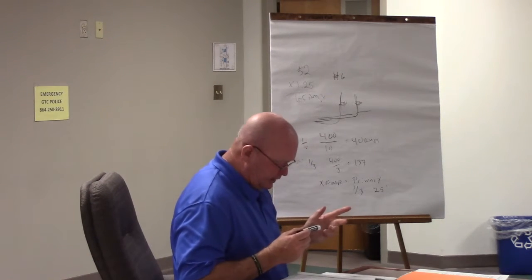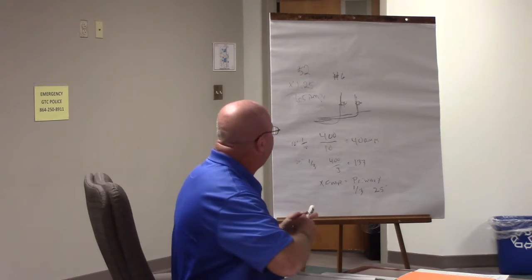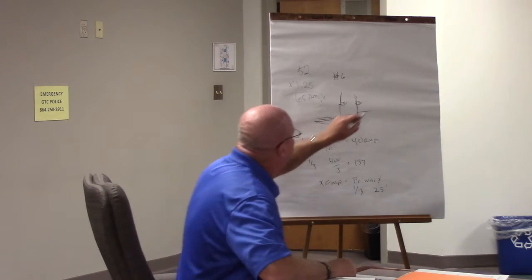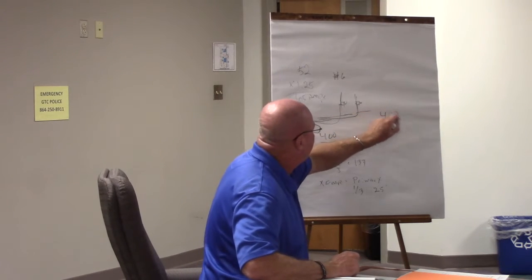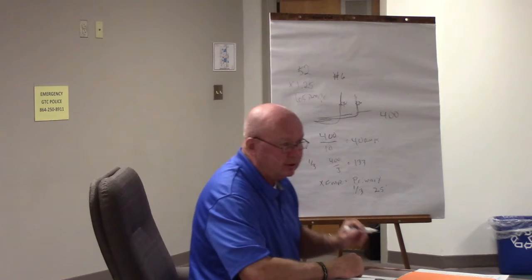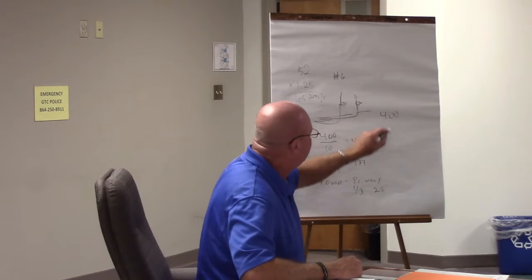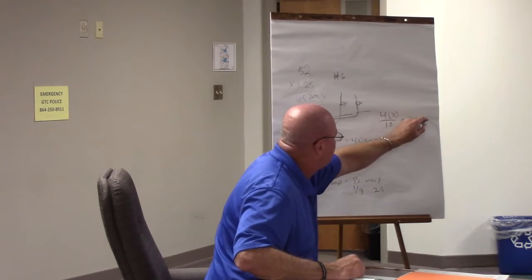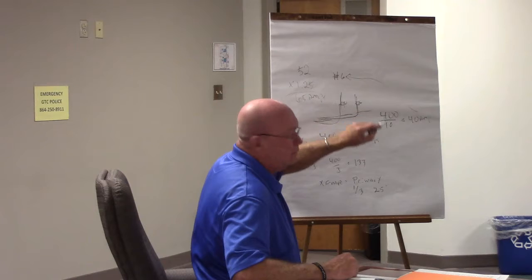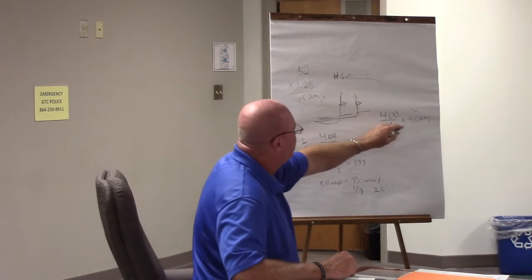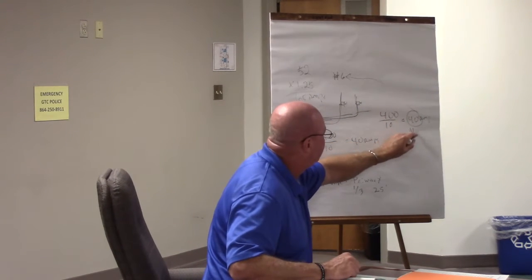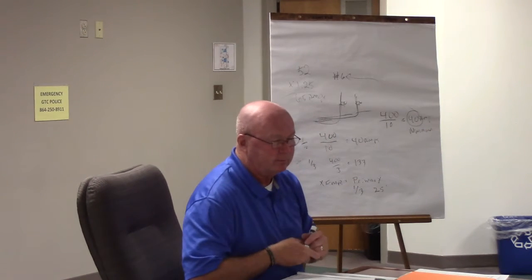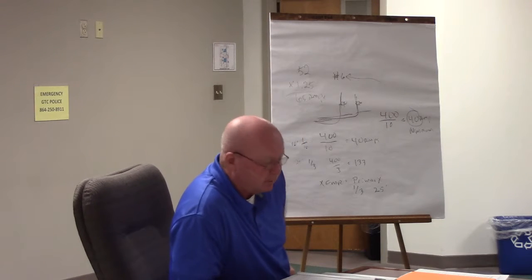All right. Will that work with our tap rule? Okay. We've got a 10-foot tap rule. What does our 10-foot tap rule say? We had a 400 amp feeder. So the 10-foot tap rule is one-tenth, so 40 amps. So can we use that? Yeah, because it meets our minimum requirement. Make sense? Not too bad.